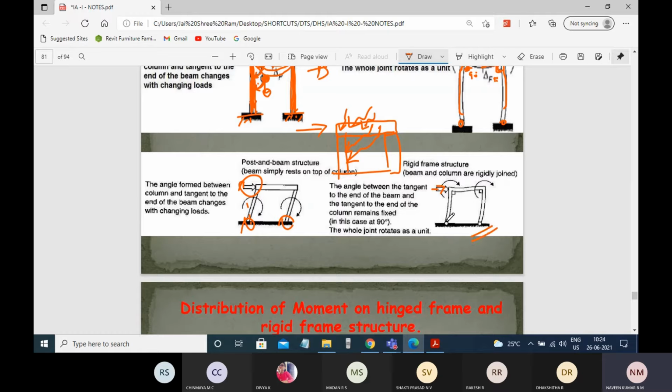Again here it is a support. Even in the support, this angle is maintained uniformly, approximately 90, and you can see the moment over here because of the rigid joint. Here there is no moment because of the hinge support, so you can expect rotation to occur.